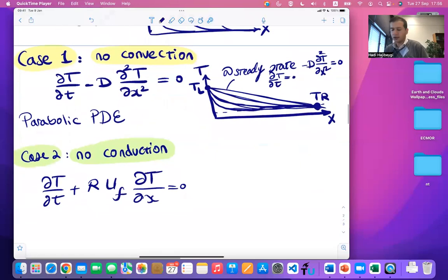That's a special partial differential equation. It's still a PDE because temperature is still a function of t and x. First order PDE, by the way, it's only the first derivative of temperature over x and t that is needed here. And it's a hyperbolic problem. Hyperbolic equation. What does hyperbolic equation mean? It means there is a sudden drop.